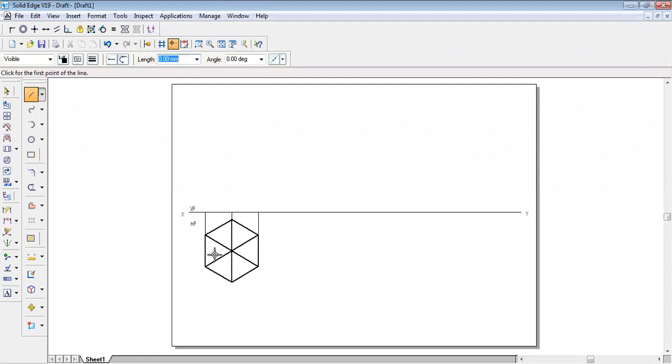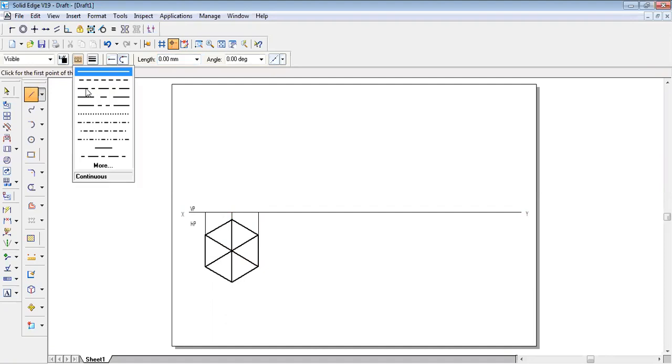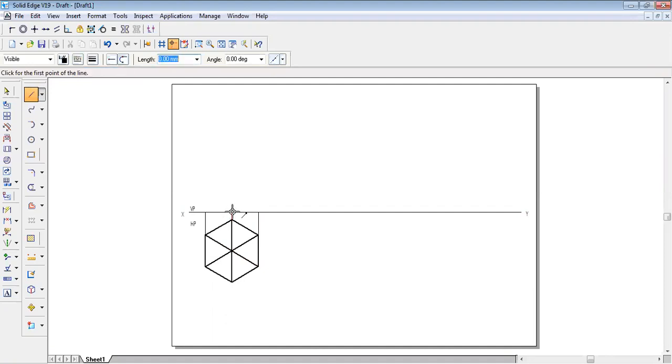Once I am projecting it, now I need to know the axis line. I'll just draw the axis line first by selecting the chain line here, that is the third line. The length of this axis, they have given it as 50 mm. So I enter 50 in the length, and angle is 90 degrees. Once I do it, I need to complete this with the pyramid. I join all the lines with the thickness of 0.5.